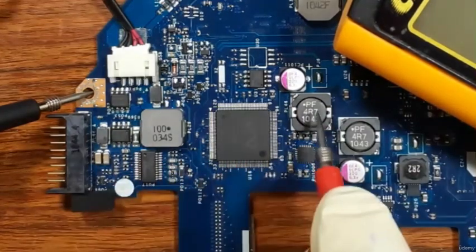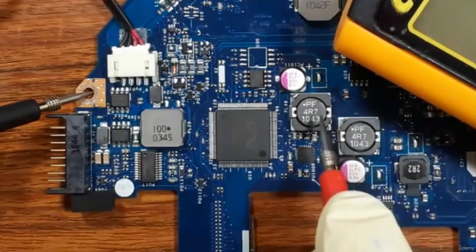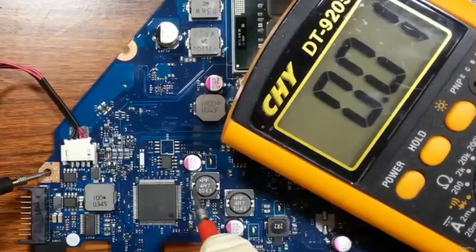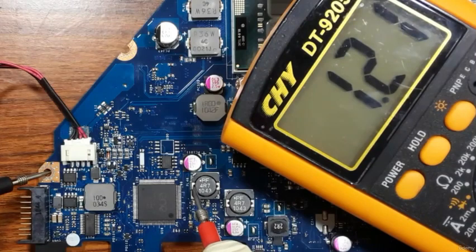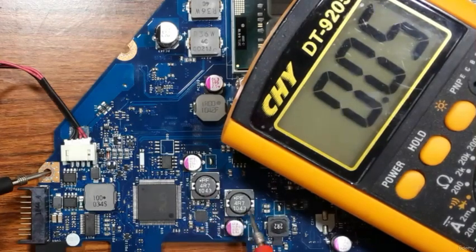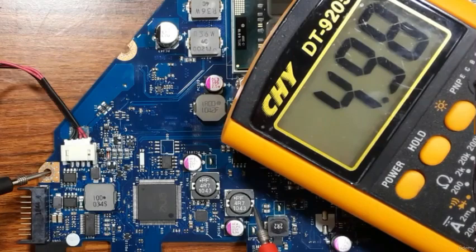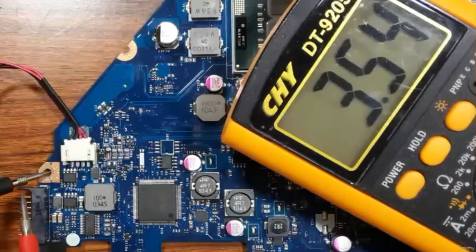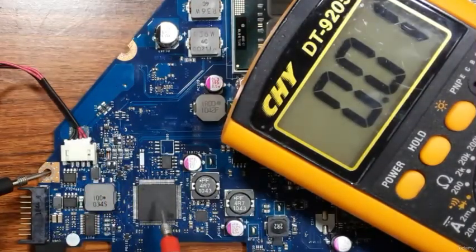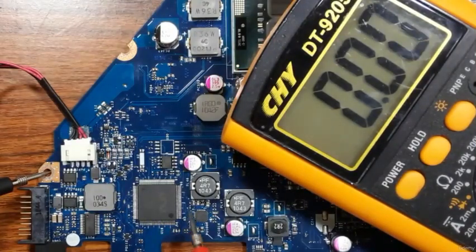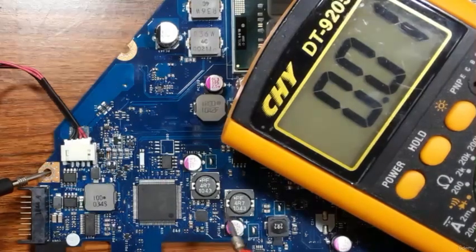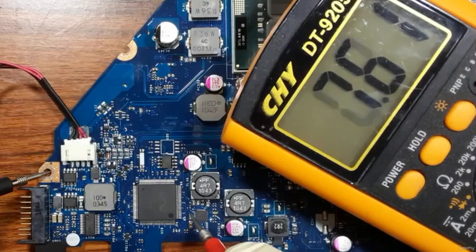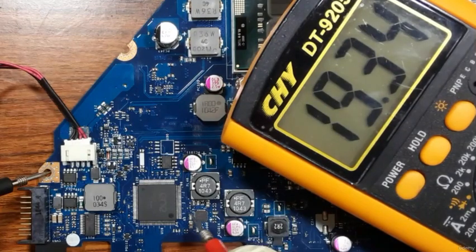So here we have two coils. It seems that this coil is for 3.3 volt and 5 volt. So let's check. Here we have 3.3 and here we have 5 volt. So this motherboard is good right here. Here this is the CPU input output. Normally if we check the capacitor near to this SIO, we should find 3.3 volts. So let's check this. For example, we have here 19 volt.